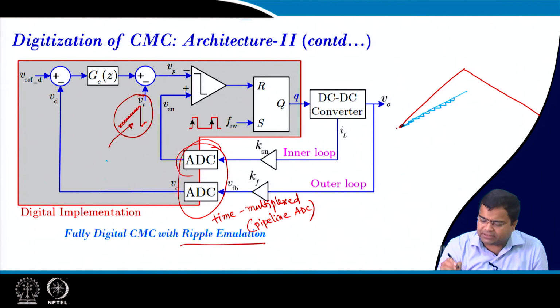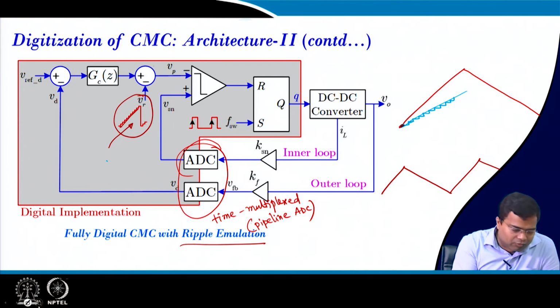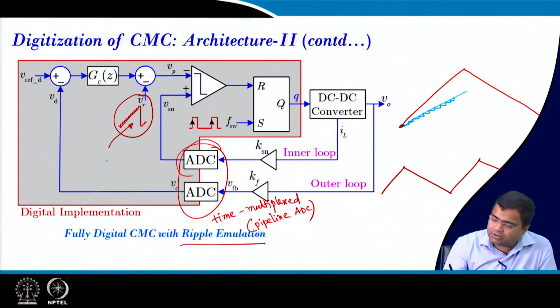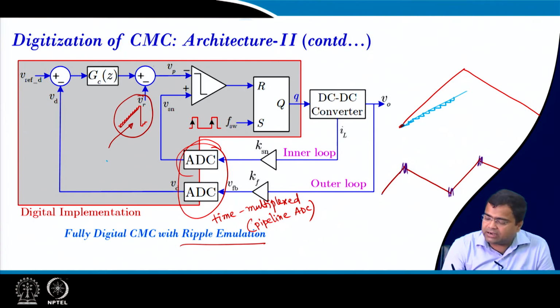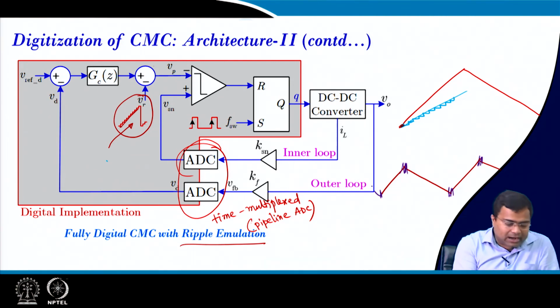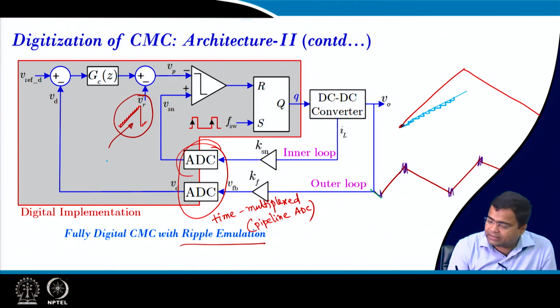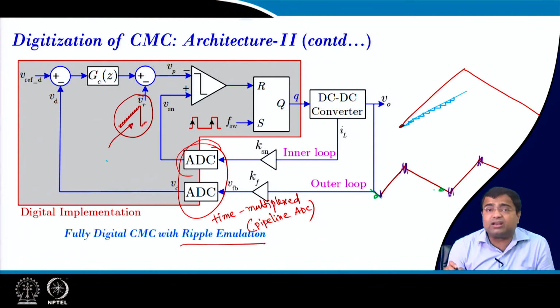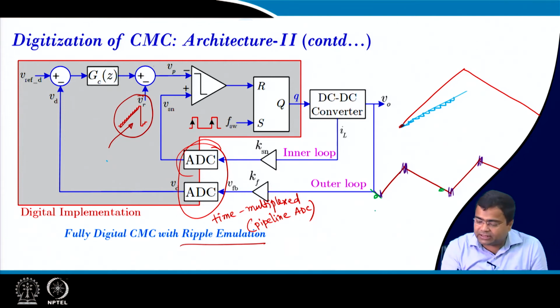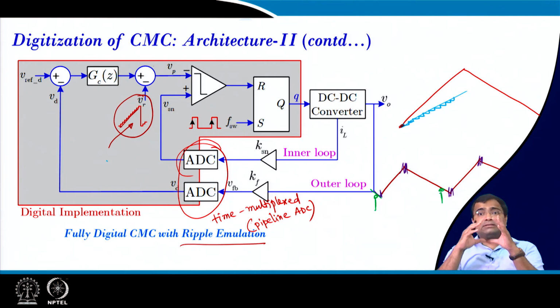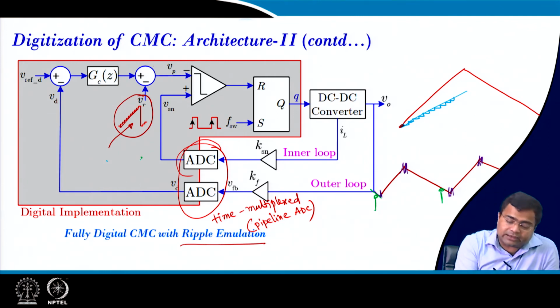Suppose I am talking about the inductor current like this. Now, when you sense current, sometimes at high frequency there can be some kind of spike here. For a very high frequency current sensor, there can be a spike. But if you take the current sample, for example, a clean current sample here before the switch turns off, these are my clean samples.